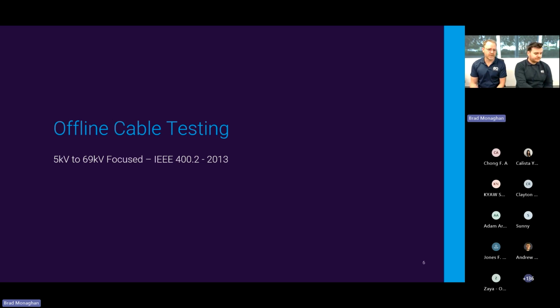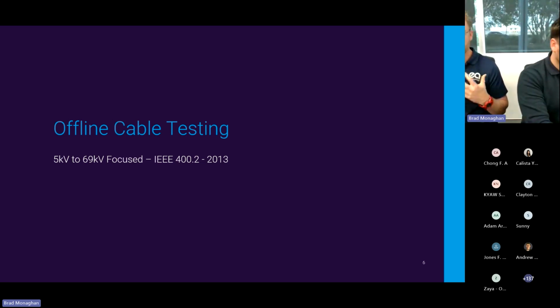All right, so let's talk about some offline cable testing. We're going to mainly focus here on IEEE 400.2, which was published in 2013. That was the last time that standard came out, which focuses on VLF testing from 5 kV up to 69 kV. We'll talk about some other tests that aren't VLF tests, but that's what we're focusing on. I'm not going to talk about factory acceptance testing, but it's mainly distribution cables that are already in the ground or have just been built.